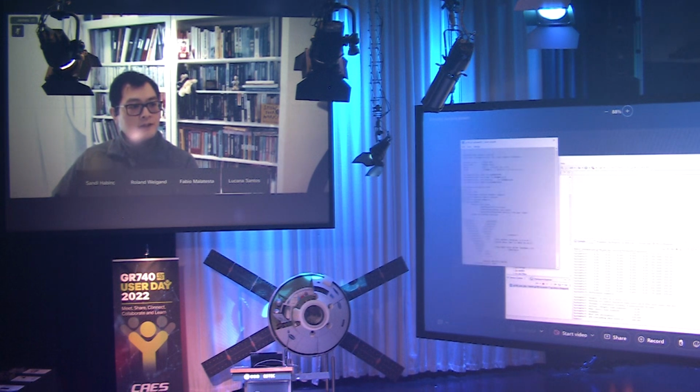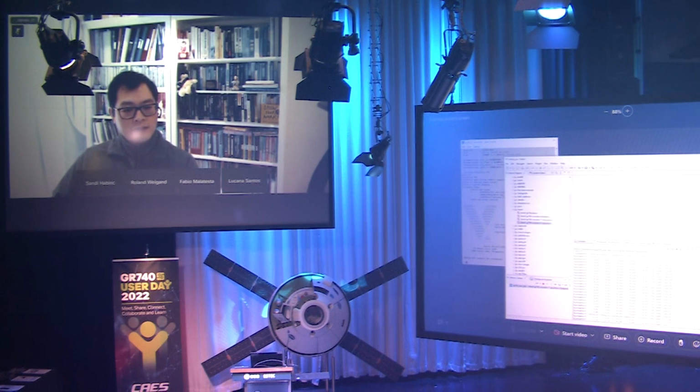It actually booted using the bootloader from Cobham Gaisler first, and then it loads VxWorks 7, and then it booted. What we see here is the impact of my live presentation and live demonstration on my simulation performance. It's executing around 300 million instructions per second, and 4 seconds of virtual time simulation takes 3.34 seconds in real time, which is a slowdown of 0.83.